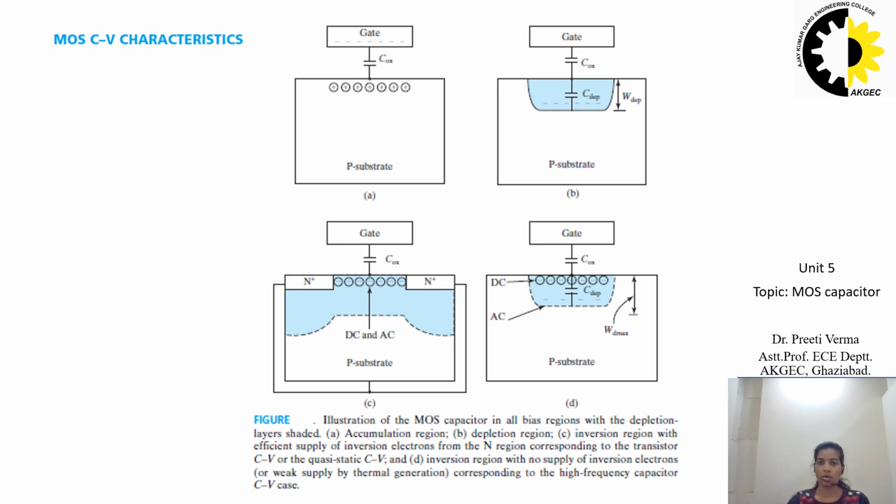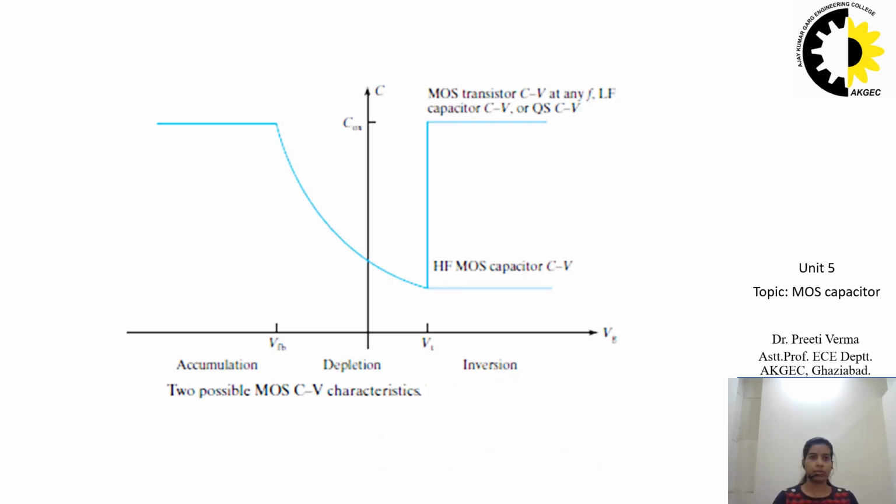Instead, the AC signal causes phi s to oscillate around 2 phi B. The change of W depletion can respond at very high frequencies because it only involves the movement of boundary majority carriers. Consequently, the AC charge exists at the bottom of the depletion region. The result is a saturation of capacitance as Vg goes to the lower side of the curve.